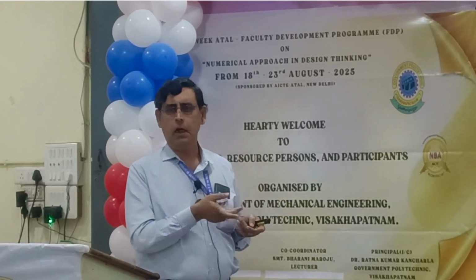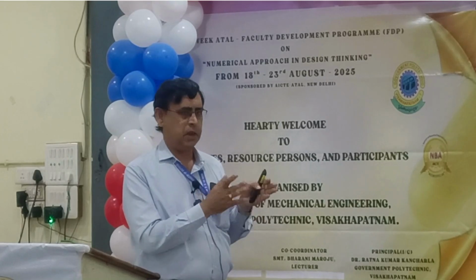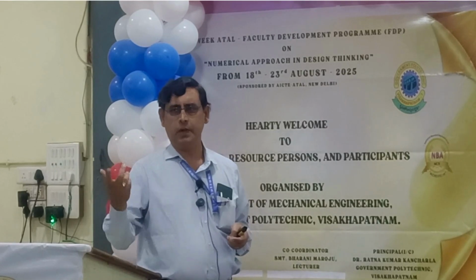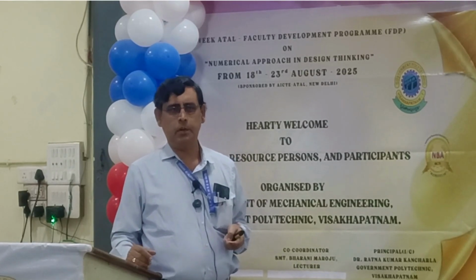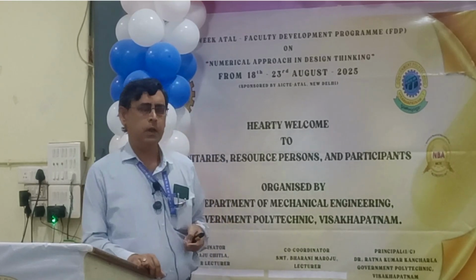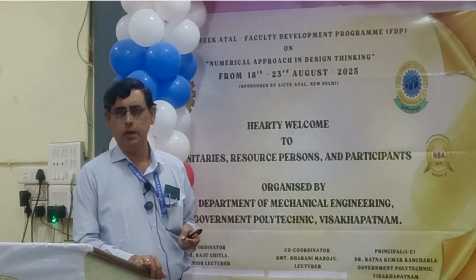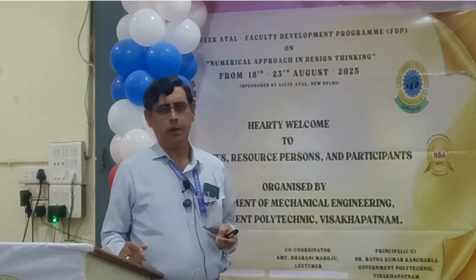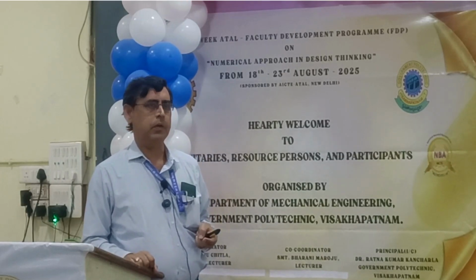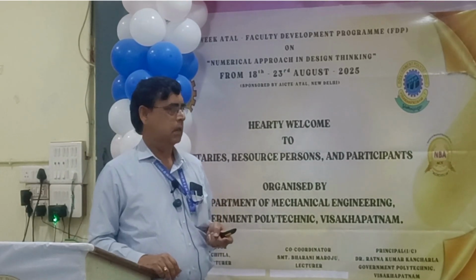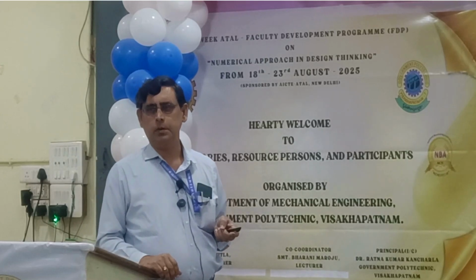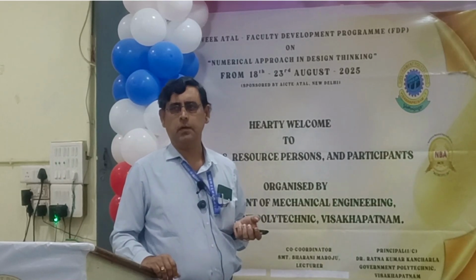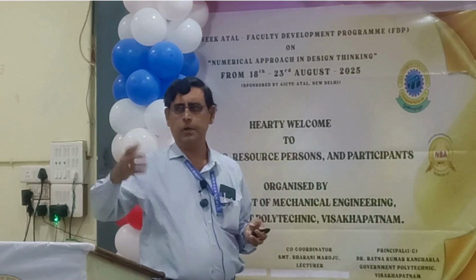Therefore, I use not only FEM, I also use BEM, because FEM has limitations at certain higher frequencies. FE cannot be used everywhere. Though finite element analysis is very popular, it is not very good for high frequencies. It is good for static analysis. It is good for normal low frequencies, etc. But when you're talking about very high frequencies, FE will not be very suitable, because the computational power requirement is too huge in case of FE. Because you have to discretize.